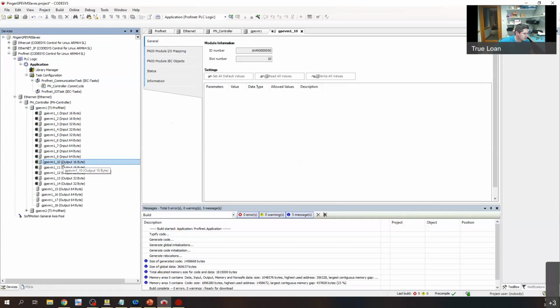I can select this first output byte, and there's many different sizes of these packets of data that you can include in every Ethernet frame. They're of adjustable size, and you could imagine that you could store different types of data in here, maybe motor position, maybe color information, things like this. The output here, I'm going to just have mapped to some LEDs, and we're going to do some cool blinking.